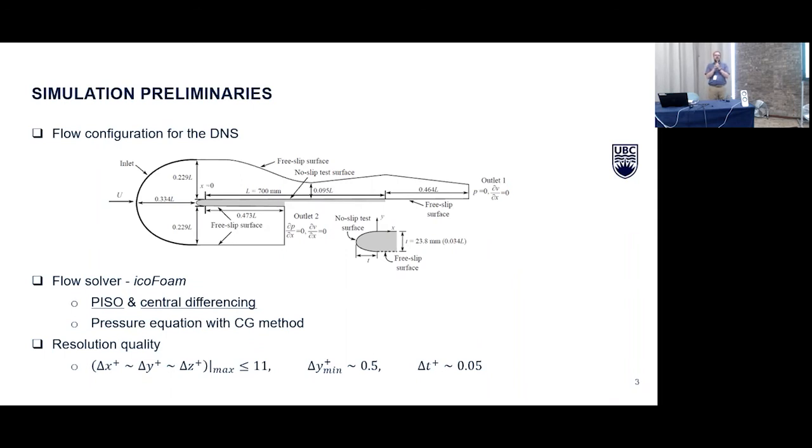I think the answer is these flat plate simulations that are idealized without the leading edge are useful for understanding the transition process by itself, to make transition models that we then put into RANS codes and use for design purposes. What I did by adding on this additional layer of complication, I don't think violates any of the prior understanding of how transition occurs. What we added on is just additional levels of, well, now this blunt leading edge results in an additional laminar separation bubble where we have this inviscid mode, which we understand quite well, coupling with the viscous mode, which we also understand quite well.